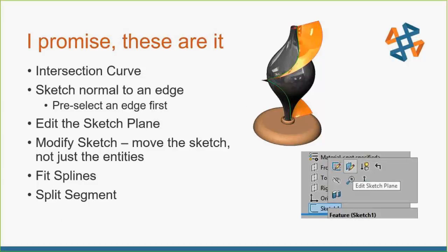So editing the sketch plane, don't forget about that one. I hope everybody knows about it, but if you don't, either left or right click your sketch. There we can see the icon right there, edit sketch plane. You can move a sketch plane from one plane to another. I've seen too many people deleting sketches and rebuilding. This can save you some of that work.